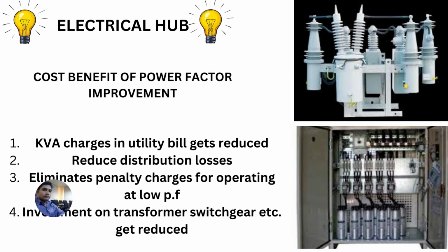Use of the capacitor bank also has a lot of cost benefit. For example, first, kVA charges in the utility bill get reduced. So, whatever kVA we are taking from the grid gets reduced. And as the current gets reduced due to the reduction of the kVA, distribution losses also get reduced.